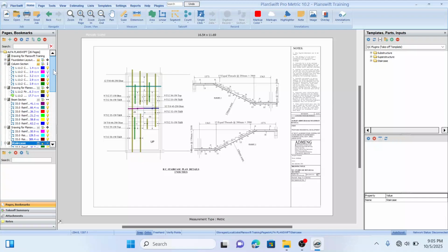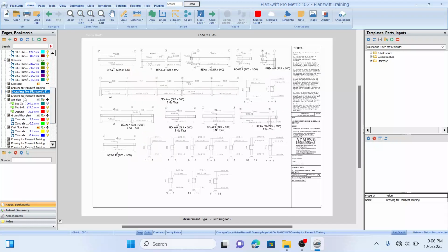And in measuring block wall, the first thing we need to do is take note of the openings in the building. We need to take note of the openings because at the end of the day, we're going to deduct those openings from the total wall area. So we'll start with openings. Then we're going to measure our block wall on our architectural drawing. So let me look at the drawing.